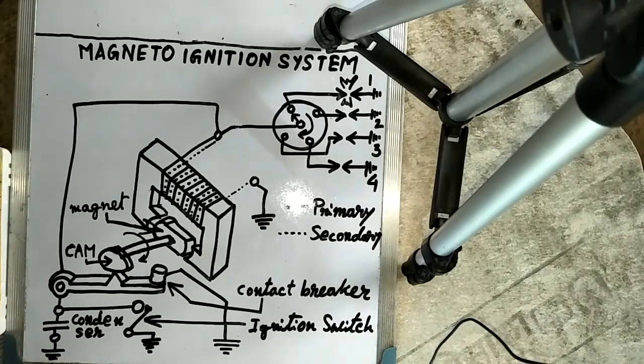The main disadvantage of the high tension magneto ignition system lies in the fact that the wirings carry a high voltage, and thus there is a strong possibility of causing engine misfire due to leakage. To avoid this, the high tension wire must be suitably shielded. The development of the low tension magneto system is an attempt to avoid the trouble.